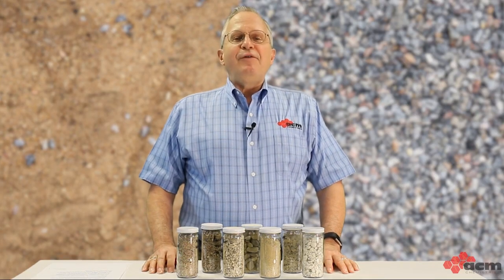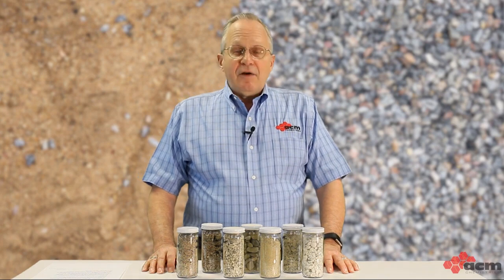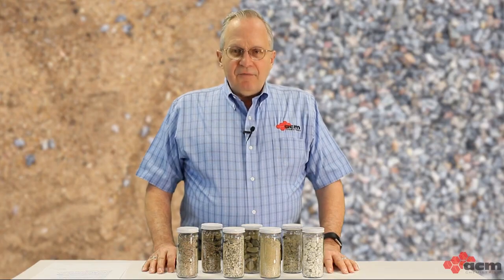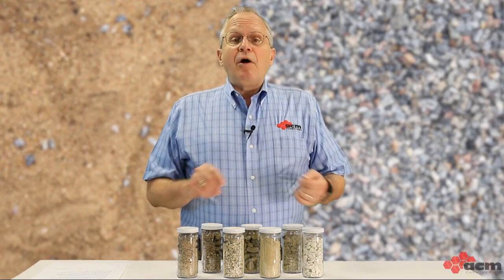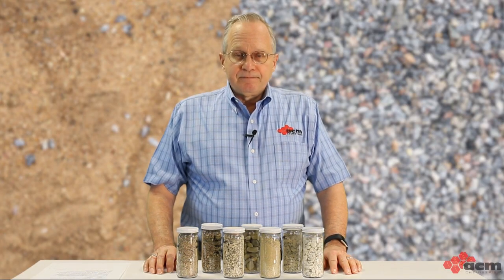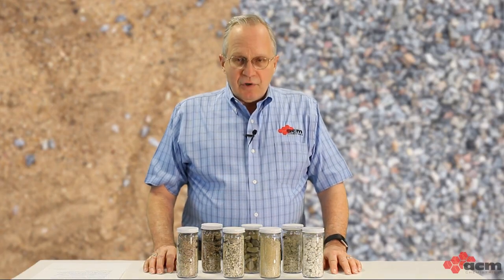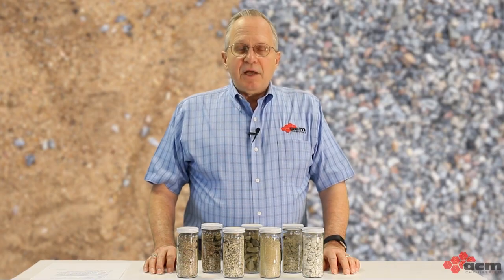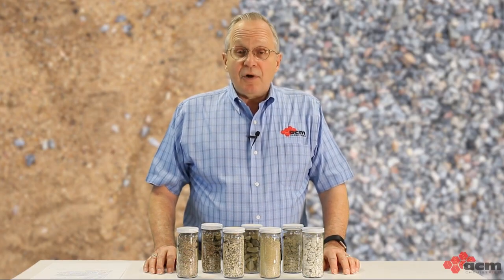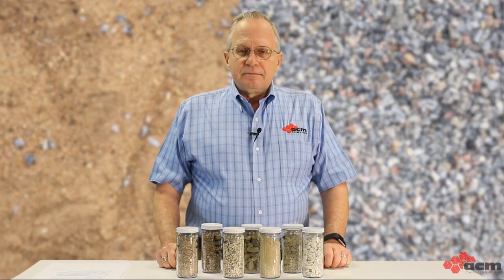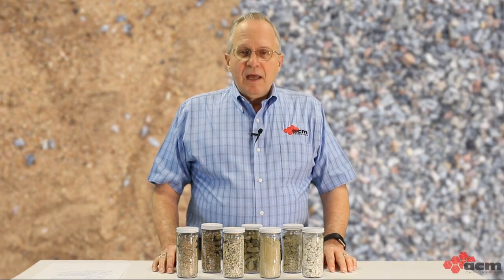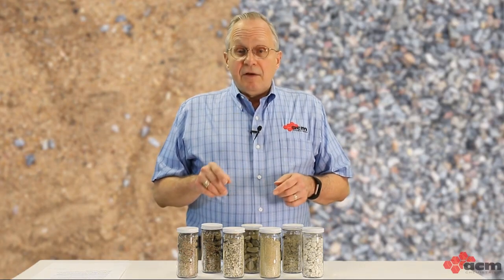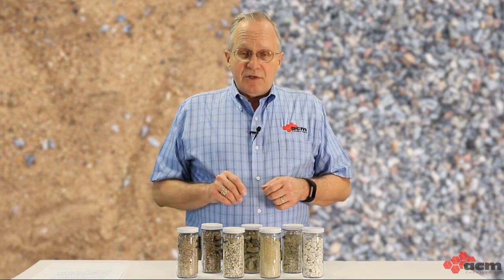So let's review what we've learned about aggregates. Aggregates are a very important part of our concrete because they're the largest component of our mixes. They influence both the appearance and overall performance of our concrete products. We use a combination of coarser aggregates and finer sands. Poor performing aggregates lead to production problems and follow-on problems like low strength and poor quality. Size, shape, and texture matter, and when deciding which aggregates to use, we determine the particle size distribution or grading of each aggregate by doing a sieve analysis on each one.